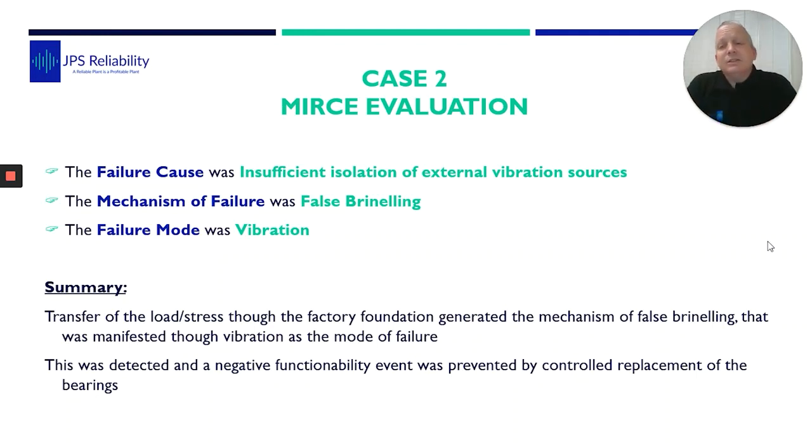So the summary on this case is that transfer of the load and the stresses through the factory and the foundation generated a mechanism of failure of false brinelling that manifested itself as a vibration mode of failure. This was detected, and the negative functionability event was prevented. So we prevented an event which affects the functionability of the system. It is managed and controlled.